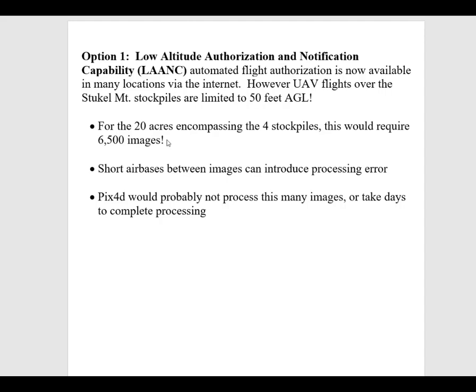I don't think the basic Pix4D software would even process that many. And if it did, the airbase, or the distance between exposure stations, is very short, and that can introduce some errors into your processing. So that wasn't a very desirable option for us.